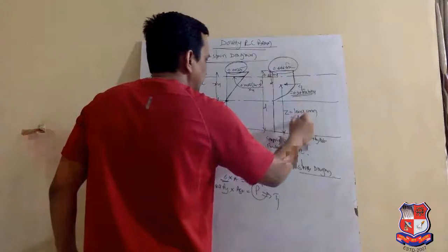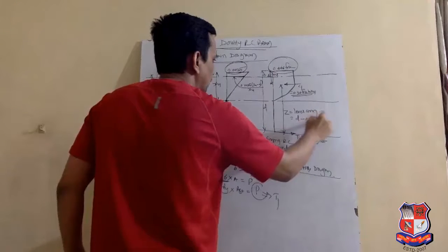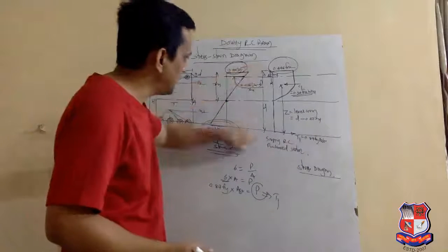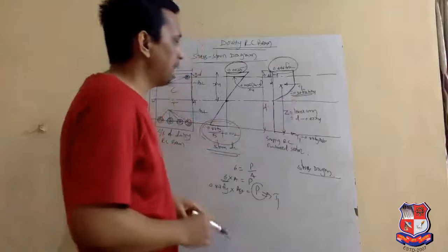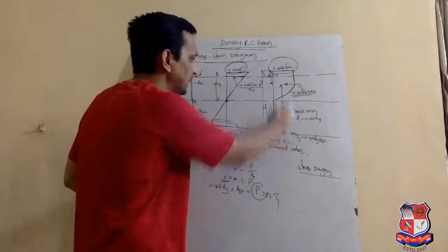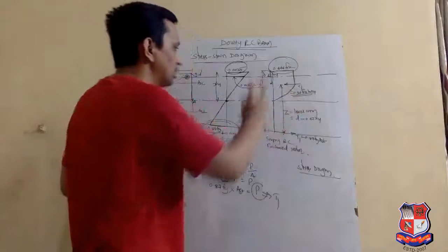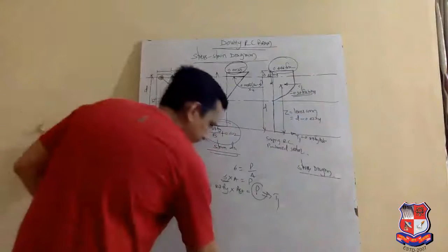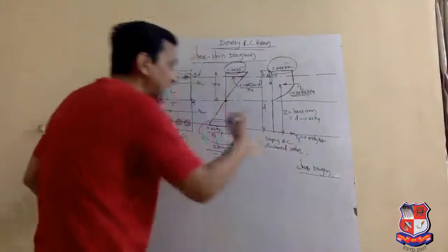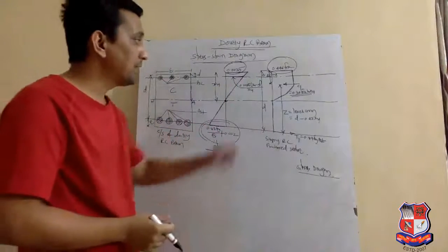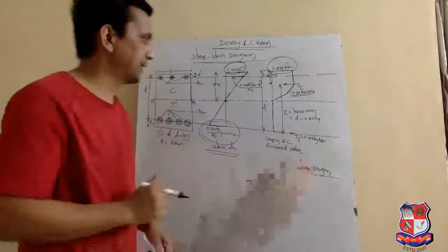So if we deduct 0.42 xu from the effective depth, d minus 0.42 xu, we get the lever arm Z, which is the vertical distance between the total compression force and the total tensile force. So this is all about the stress diagram of the singly reinforced balanced section of the doubly reinforced beam.